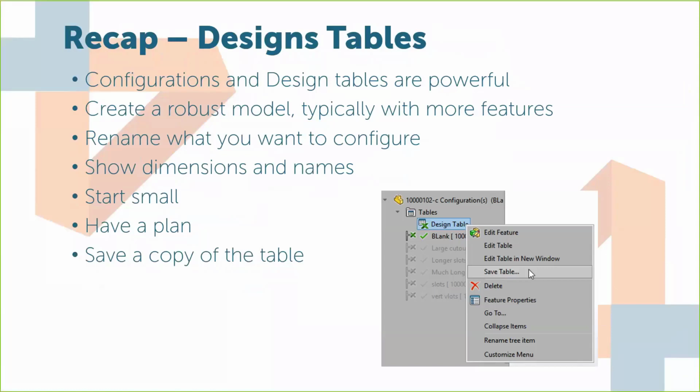With design tables, if you're not familiar with them, start small. Maybe brush up on some Excel functionality. If you're like me, that's definitely a good thing to do. Have a plan, and large table or small table, save a copy of the table. If it's an external design table, save a copy of that external design table. We don't want anything unfortunate to happen to these tables. That's for sure.